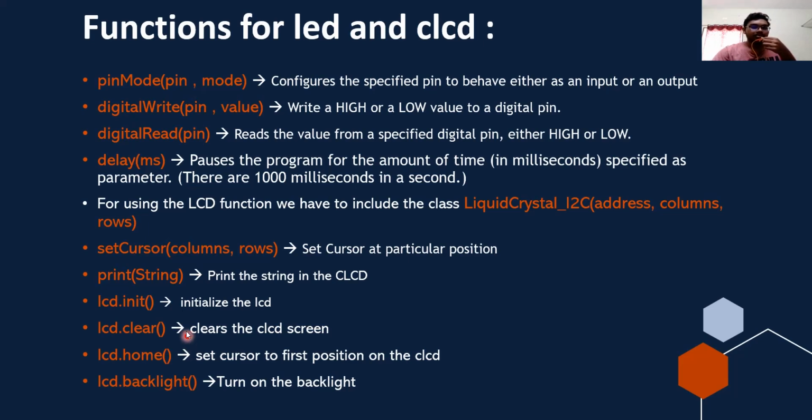And you will be using setCursor(column, row). In columns you will have 16 columns, but you will have 2 rows, to set the cursor at a particular position. And print, lcd.print, will just transfer the data to the LCD, and it will get printed there.